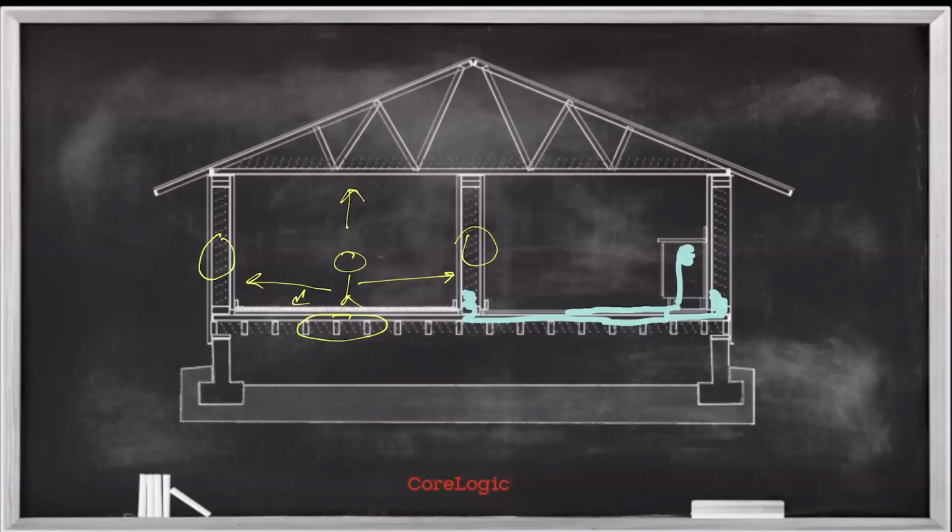And one of the things that I'll always stress is that the moment you find unaffected materials, document it. Those that have been through any training with me before, hopefully you've heard me stress that before. You have to check everything that can be reasonably expected to be wet. You then have to document everything you check. I don't have to measure every material in a building, but I have to measure everything that could reasonably be wet. And then I have to document everything I check.